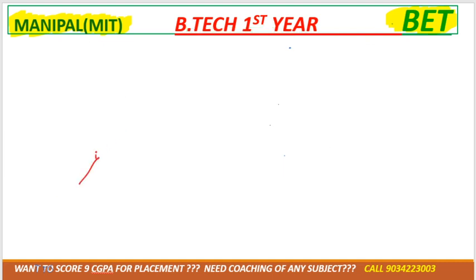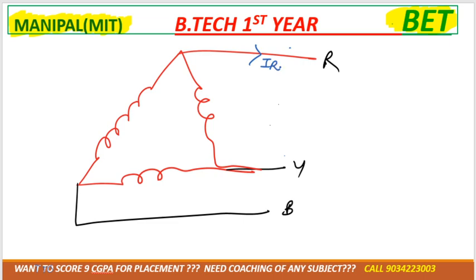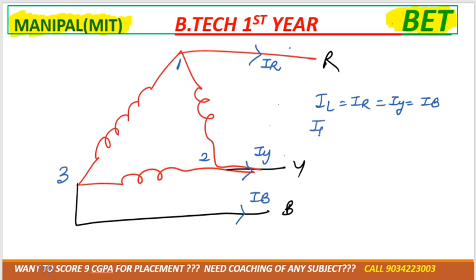Now after that, similarly, we'll draw the diagram again for the delta, and now we'll mark the current. So it would be again R, Y, B. Current over here is IR, IY, and IB. This is 1, 2, and 3. So what is the line current? IL would be equal to IR, equal to IY, equal to IB. And phase current would be IPH, equal to I12, equal to I23, equal to I13. Now suppose if I mark the current, this one would be I12, this one would be I13, and this one would be I23.